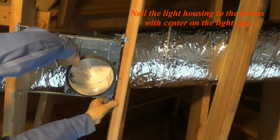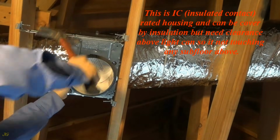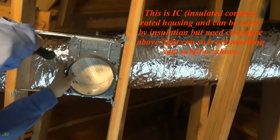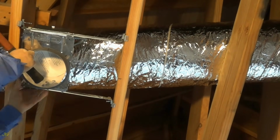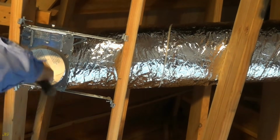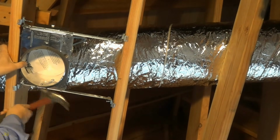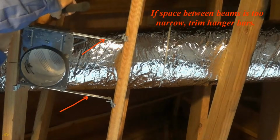Nail the light housing to the beams with center on the light can. This is IC, insulated contact, rated housing and can be covered by insulation but needs clearance above light can so it is not touching any subfloor above. If space between beams is too narrow, trim hanger bars.